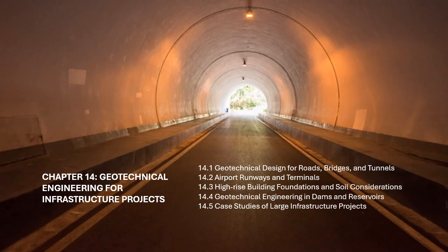Foundation stability. The foundation must be able to resist sliding, settlement, and overturning forces. For concrete dams, engineers assess the shear strength of the rock or soil beneath the dam and design the foundation to distribute the weight evenly. For earthfill and rockfill dams, stability analysis is crucial to prevent failure due to slumping or excessive settlement.